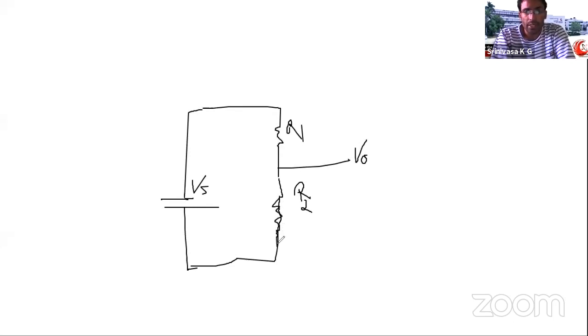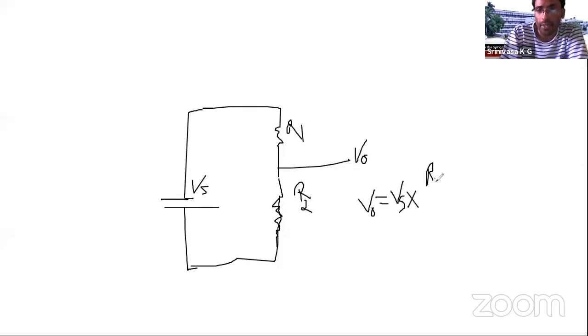Don't get confused about resistance. So over here, what will be the output voltage according to resistance? What will be the formula? So this one will be the formula. V output is equal to V supply, whatever supply voltage we are giving, multiplied by R2. So above side there will be R2 and below side will be the sum of two resistances, R1 plus R2.